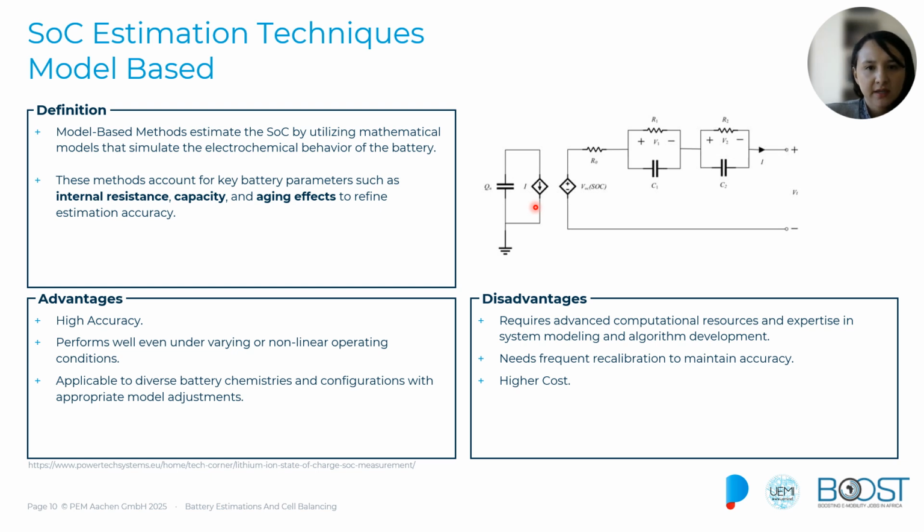These models in general involve a lot of different steps. For instance, at the beginning we have to create the mathematical model and to have an initial characterization of the model with, for instance, this type of equivalent circuit models, and to develop this to represent as closely as possible our battery system. Then we need to find each of these parameters, such as the resistance, the capacity, and so on. And all of this is derived from experimental data and from the continuous experimentation with our system. The more we have experimented with our system, the more accurate these parameters will be.